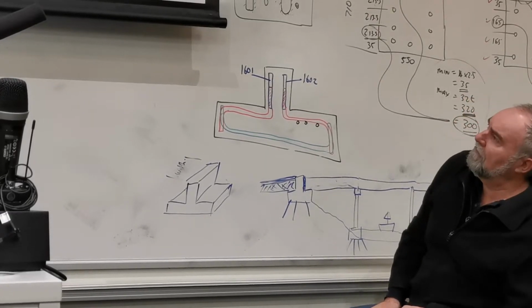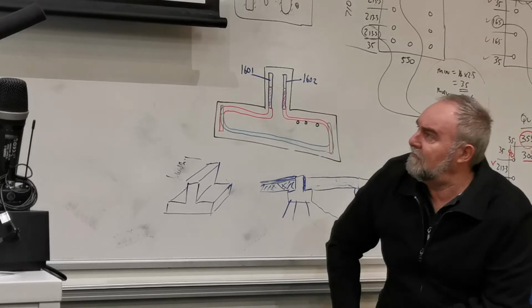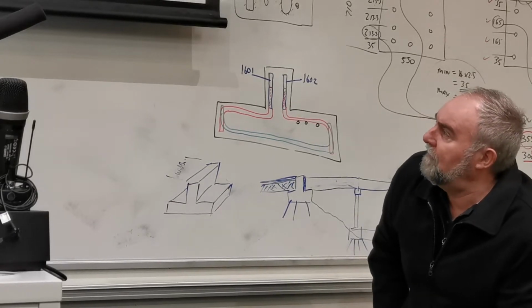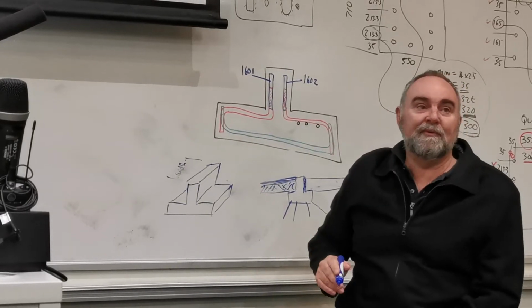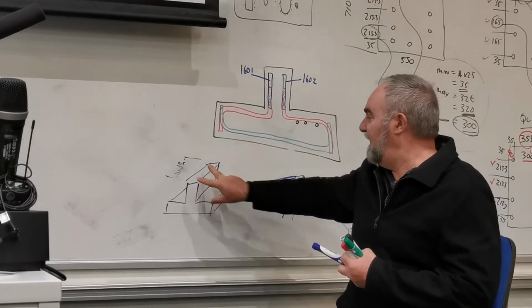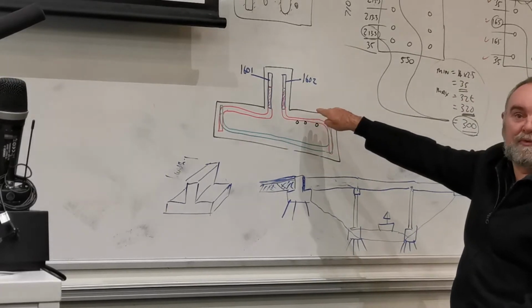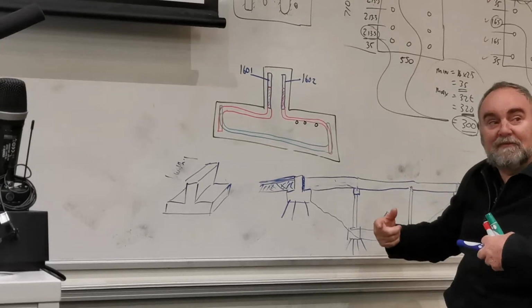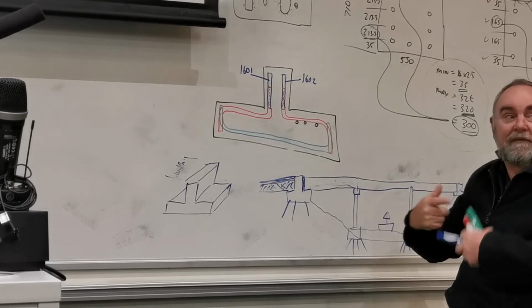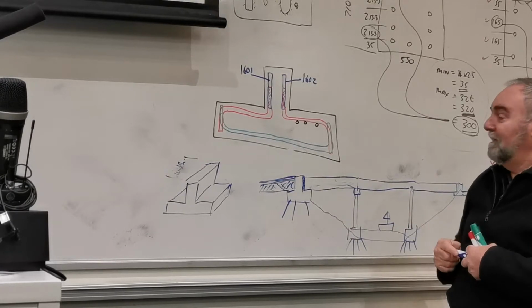Is that right? 3 point something. Down the bottom, sorry, of that page. Width of 3.7. Yeah. So in your case, the width is 3.7. So that's that distance there, which means the distance it goes into the wall. All right. So we don't refer to it as the length, we refer to it as the width. So it's the width of the abutment.